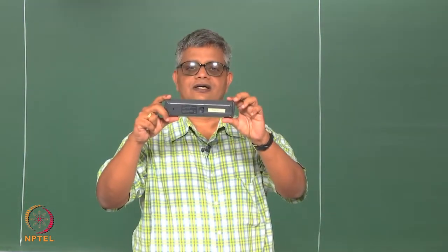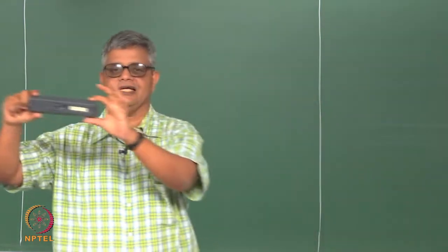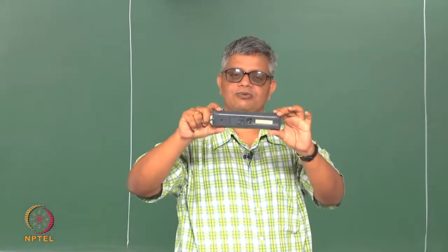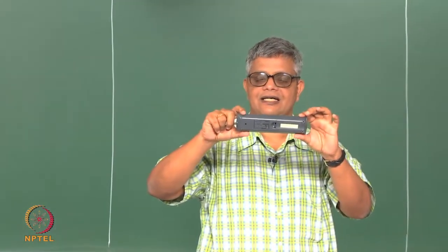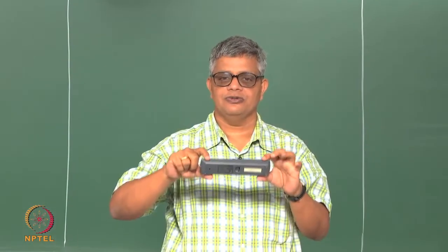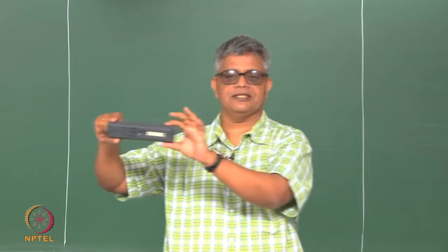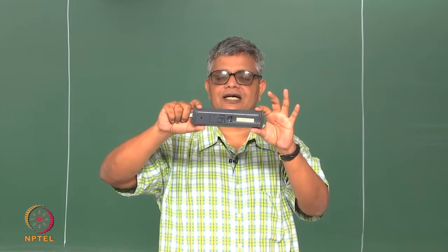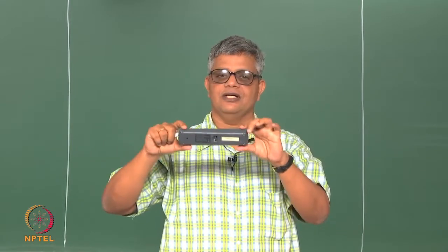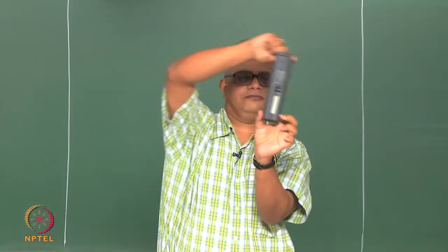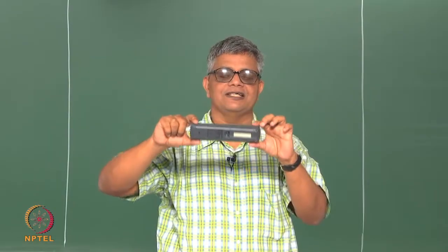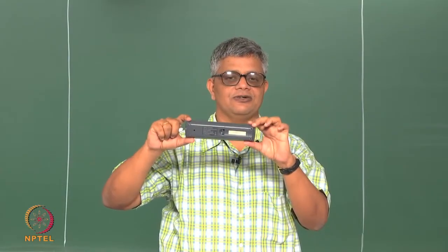For example, if this is a solid body, you can have pure translation in the x direction or in the y direction. This is one form of motion that a fluid element goes through, and in the case of pure translation in any direction, the fluid element does not get any deformation, it remains the same. You can have pure rotation along the diagonal of this, and here again we can see that the shape does not change.